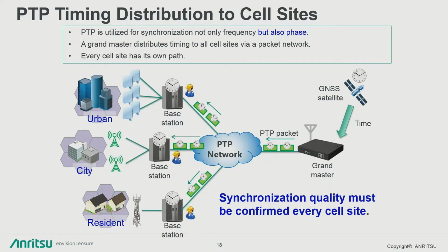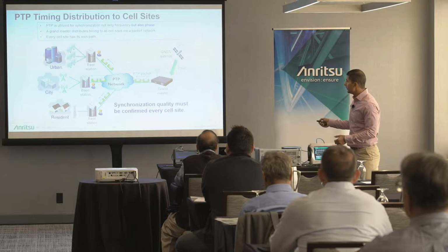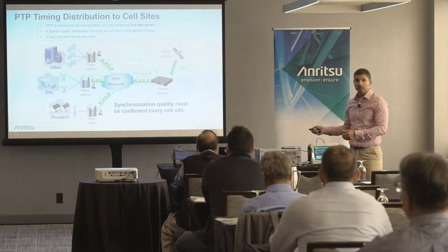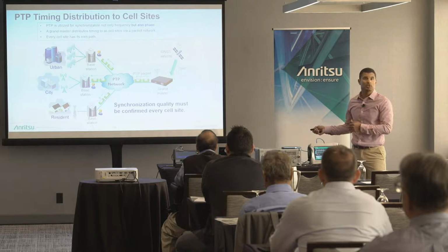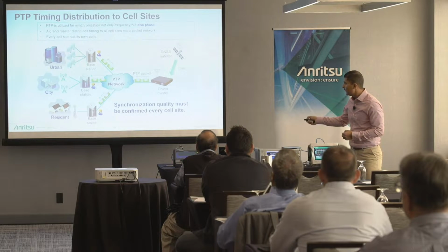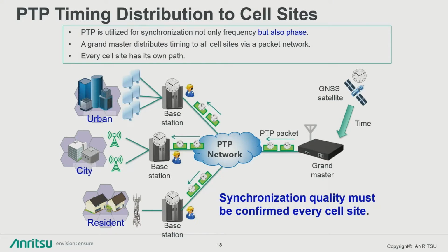It's nothing new. It's basically the ability to take synchronization from a grandmaster site, your reference point, and distribute that timing through your already existing fiber optic network. So think about this. Instead of having GPS at each one of your base stations, especially our 5G small cells, you're able to have one grandmaster site, a clock receiving its master timing. This could be at a GPS site, distributing that in Ethernet packets through your PTP network to various base stations.